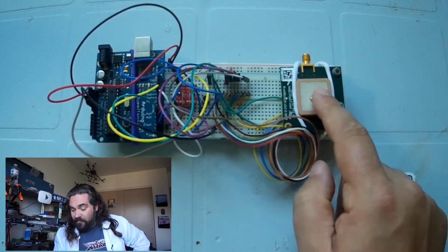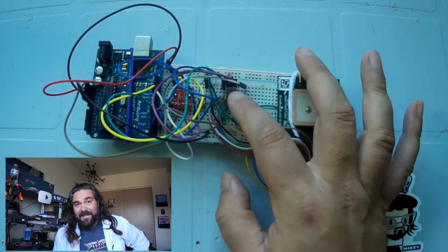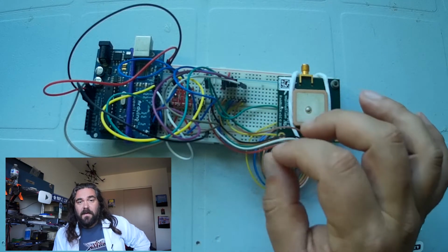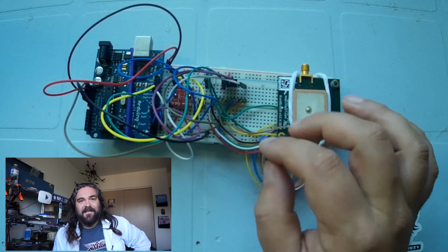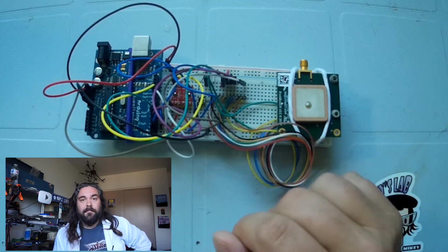We have our Rockblock module with our breakout header. We have several pins connected here, including the one that indicates when satellites are available. That is a very, very good piece of breakout that doesn't exist with the header that comes with this, so make sure that you buy the additional pinout header. We have another pin here as well that lets us put the module to sleep. That will allow us to get the maximum battery life out of our project.